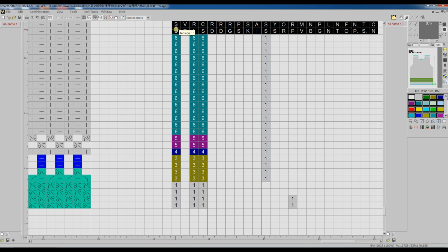You can change the tension number manually here. Dynamic stitch tension setting is only available on imported machines, Stoll and Shima Seiki. You can fill in color number above 65 to turn on this option. After translation, the feeders will kick back like during partial knitting to perform different tensions on the same course.